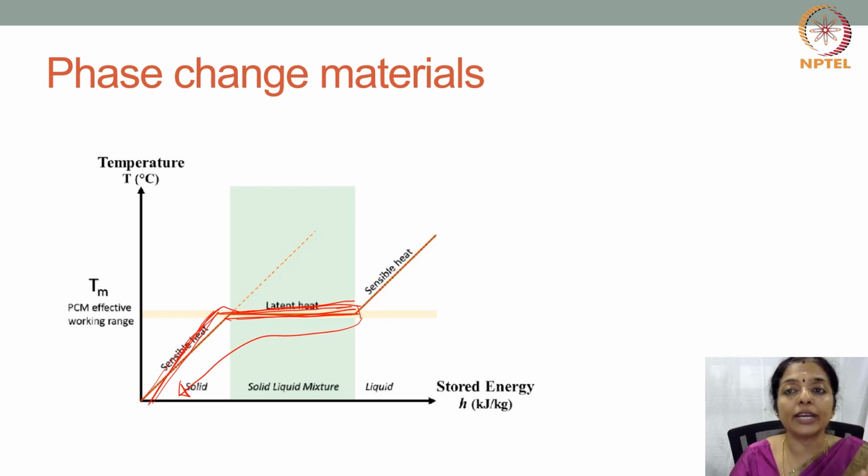at specific temperatures. So phase change material incorporated glazing units refer to innovative building material that combine phase change materials with glazing systems in order to enhance the energy efficiency of buildings. These units aim to address the challenges of regulating indoor temperature by leveraging the latent heat absorption and release properties of the phase change materials.